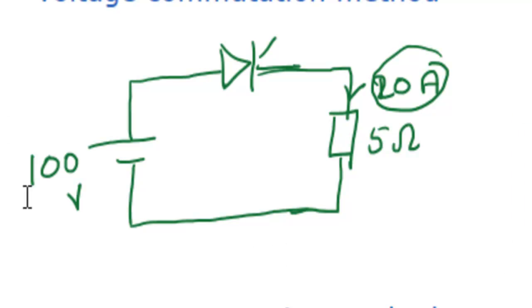In case of an AC source, this voltage will reach the maximum and then slowly go back to zero. At the time of zero, the load current will also be zero, and then the thyristor current will be zero. At that time, this thyristor will be turned off. But in case of a DC source, that won't happen, because this is constant voltage, then constant load, so the current will be constant. So to do this, we require the commutation circuit.